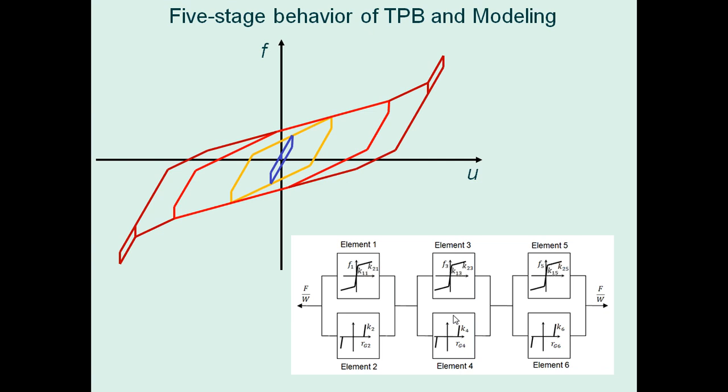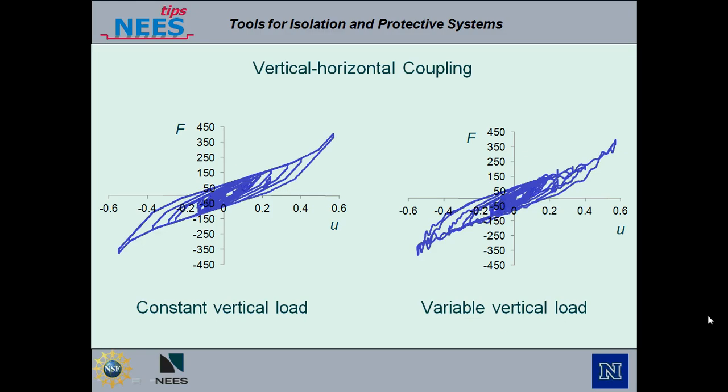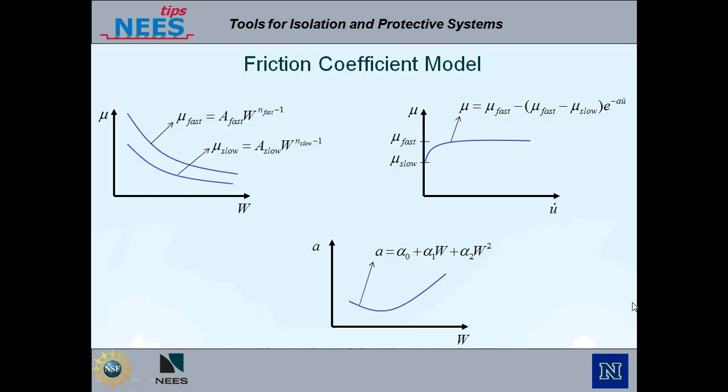The developed self-contained element accounts for the bidirectional interaction in the horizontal behavior. The horizontal response of a friction bearing is dependent on vertical load, and this dependence is accounted for in the developed element. The dependence of friction coefficient on both vertical load and velocity is also accounted.